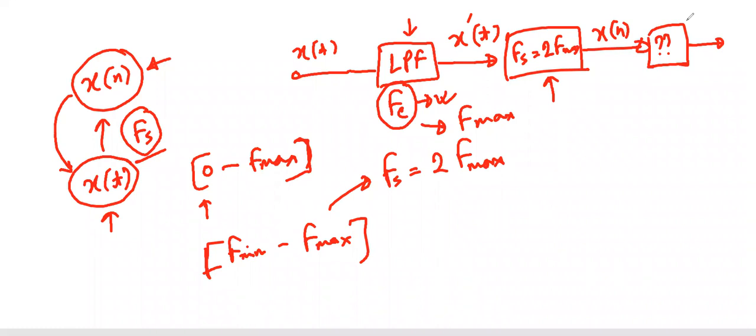All through the lecture, we have represented our aliasing signal as negative, in the sense that it destroys the signal and changes the originality of the signal. However, there is some purpose of the alias signal. By using the alias signal, you can compress your signal from a higher frequency to a lower frequency. Probably we don't have enough time to discuss this, but you can search for it: what is the use of the alias signal in signal processing?